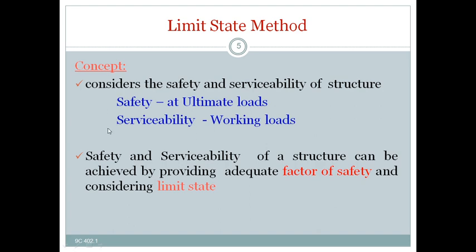So by considering these two parameters, safety and serviceability, in this limit state method, how do we achieve it? How can I say my structure is very safe and my structure is serviceable, and how do we achieve these two criteria in the limit state method? Right. The safety and serviceability of a structure can be achieved by providing an adequate factor of safety and by considering the limit state. As I discussed in our last class, what is that limit state and what is the factor of safety.